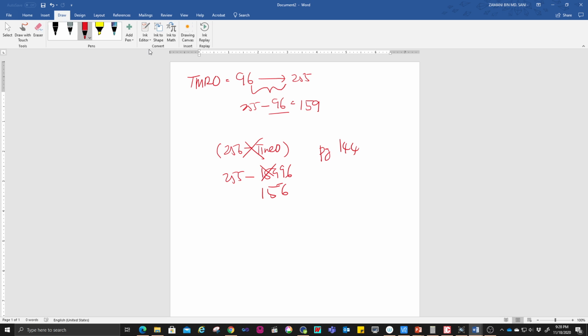So we can get the results here. It's going to be F out. Remember that this is F clock, divide by 4, divide by the prescaler, divide by 2, divide by the timer 0 counting, because this is the number, right? This is the one: 156 and times 1 count.